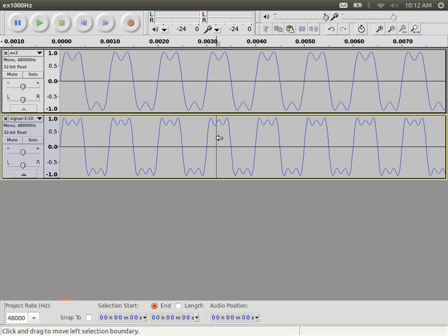If we highlight this period, we can transmit 2 bits in a time frame of 1 millisecond. It's the same as our first signal, the same as A. Note the frequency is the same, therefore the period is the same. Therefore the number of bits we can transmit in a period gives us the same data rate as A.